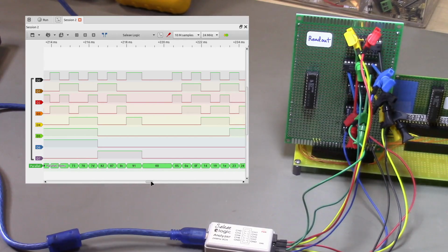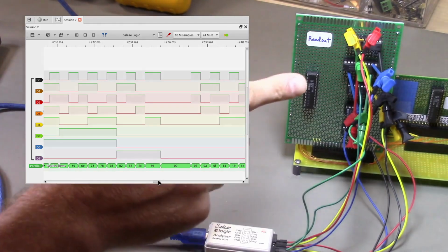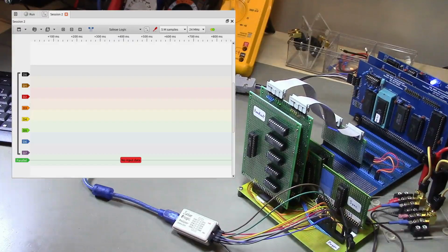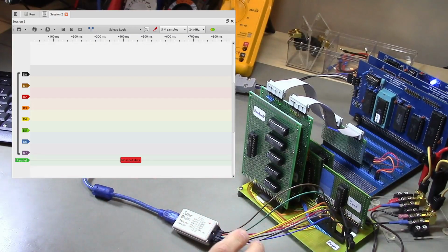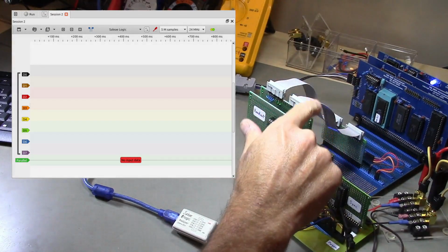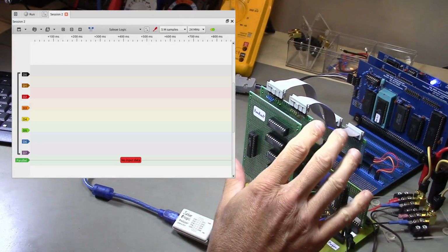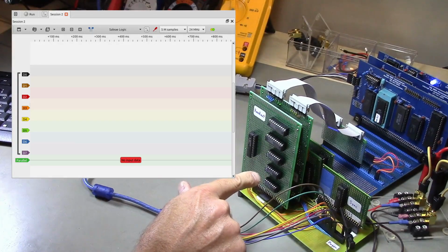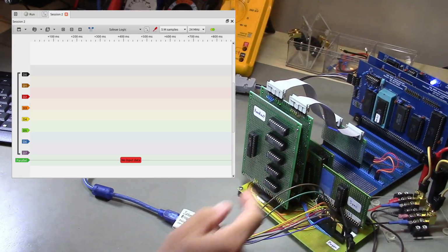So this is a pretty exciting result because I think it does indicate that our readout module at least potentially is working correctly. All right, so here is the second test I want to do, and let me describe what is going on here. I have the 6809 system hooked up, and I have the VRAM module installed, so that's pretty much the same as the setup from the last video, but I now have the readout module here, which is generating VRAM addresses that are sent to the display controller side of the VRAM module.